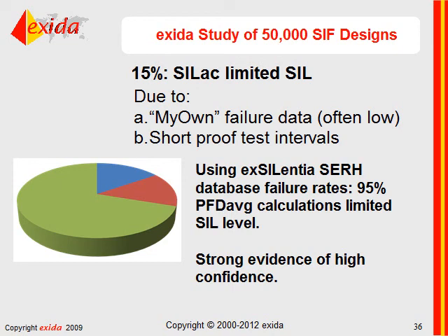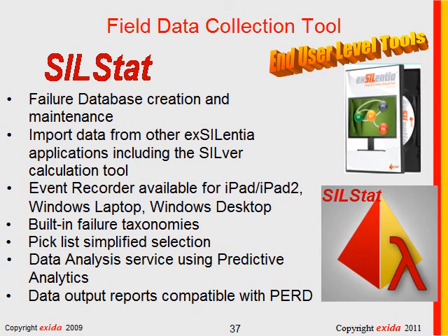So the bottom line is that 95% of the time, the PFD calculation gave the correct SIL verification result. To me, that's very strong evidence of high quality data. That doesn't mean we don't need to do better in the future. As we all move forward, the advantages of high quality field data collection will become more and more apparent, in my mind, especially for maintenance-induced failures and systematic failures.